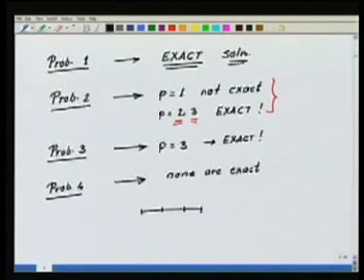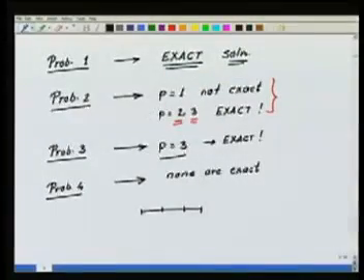Now, how are we going to approximate? You can take, let us say, 3 elements in the domain. Okay. So, 3 elements of size 1 by 3, 1 by 3 and 1 by 3, and do the whole thing. But what we are going to see, in the cases when it is not exact, is that if I refine the mesh, that is, I add more and more points, I should get closer and closer to the exact solution of the problem.